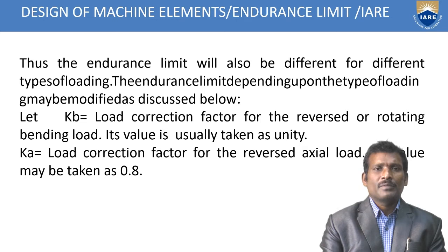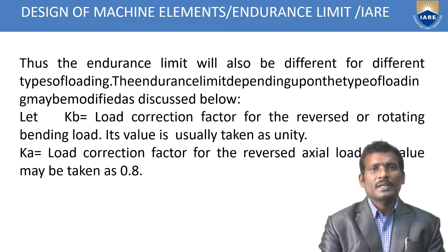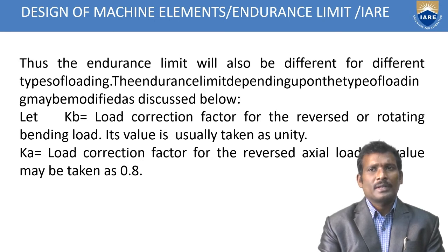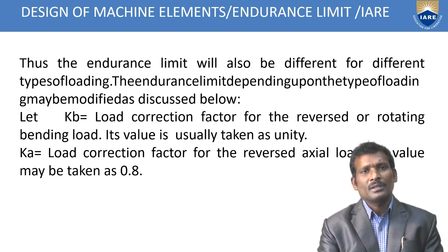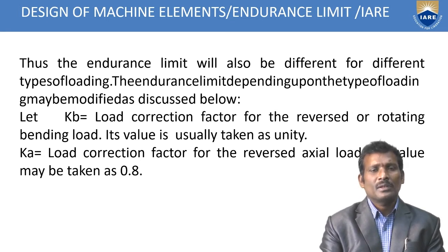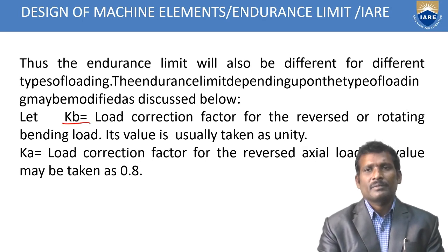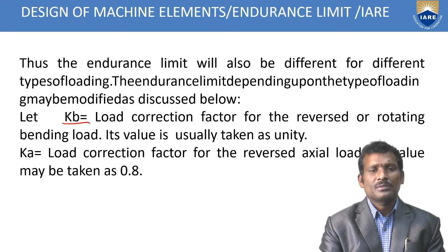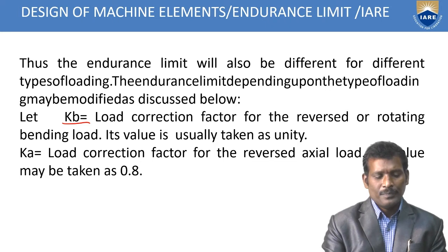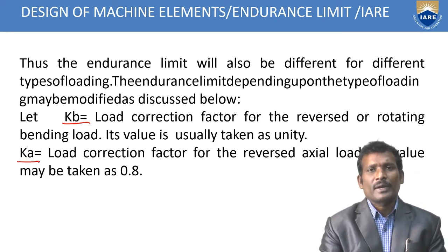Thus the endurance limit will also be different for different types of loading. The endurance limit depends upon the type of loads, the type of material, and the geometry of the component also. Let Kb be the load correction factor for reversed bending loads. Its value is always taken as unity, that is 1.